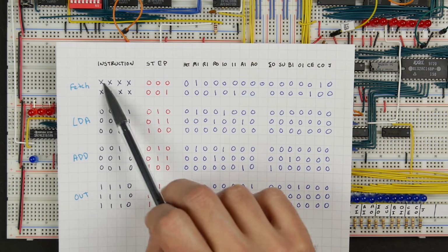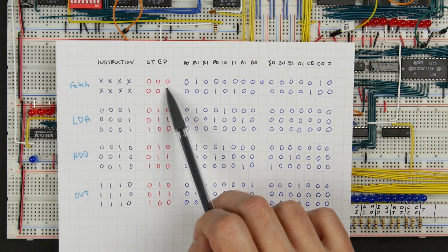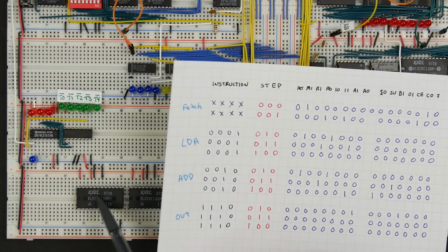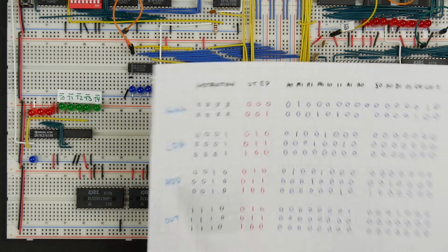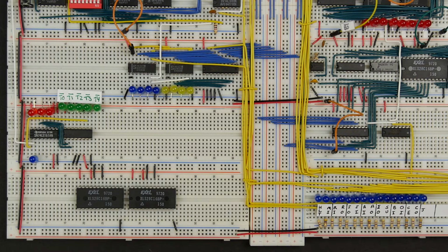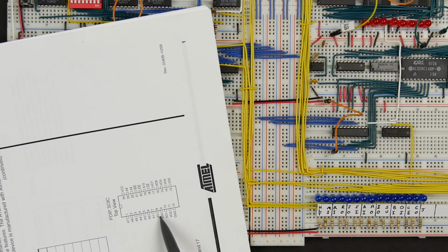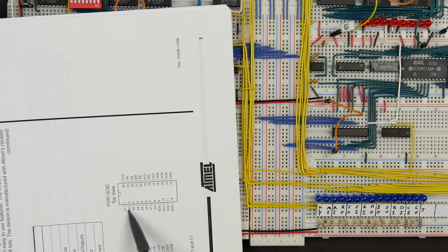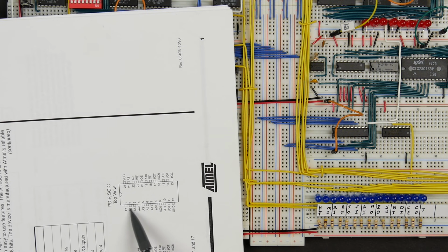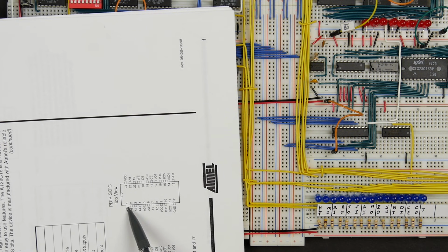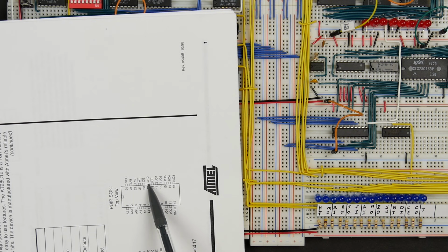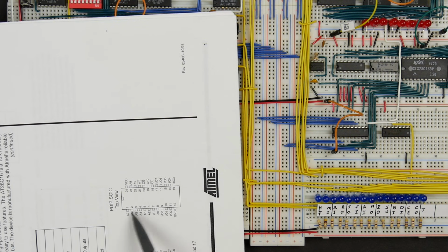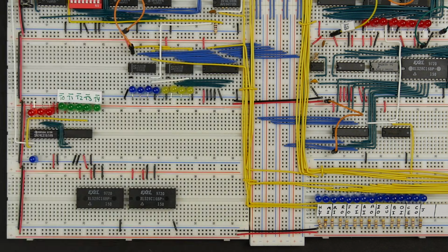And so there's only 7 bits there for that address. And each of these chips has an 11-bit address. So we want to make sure that our address is going to come in here on A0 through A6, those first 7 bits of the address. But then A7, A8, A9, and A10, we're not going to use those. We just want to tie all of those to ground. So I'm just going to do that now.